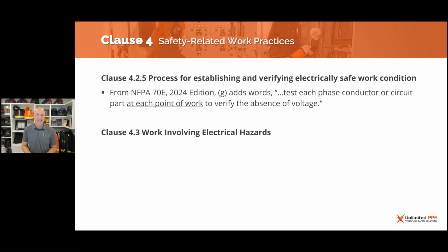There in Z462, there's an 8-step procedure that shall be followed. And one of those steps is the verification of absence of voltage. And we've added a requirement within that step that the worker shall test each phase conductor or circuit part at each point of work to verify the absence of voltage.